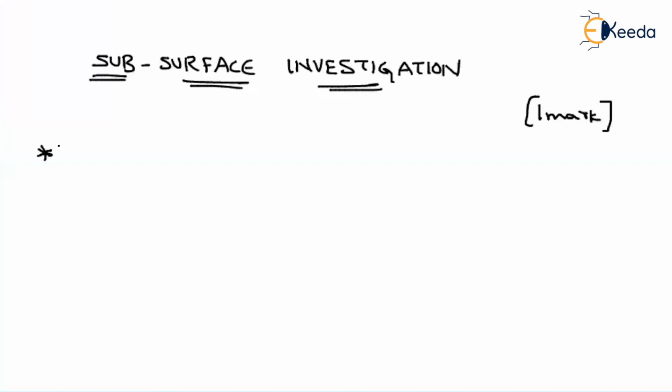If it is a normal residential building, like up to G+1 or only a ground floor, in most cases in villages they won't do any soil investigation. Why? Because in a mandal there will be some limit, like design up to 2 floors or 3 floors. They have already surveyed the village and collected soil samples. Based on that, they will tell you to design up to 3 floors only, or 2 floors only. So if you have that limit, there is no need to check the soil properties again, because the government itself has already given you some limits.